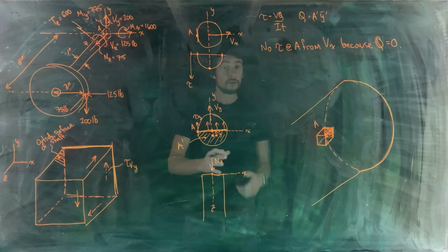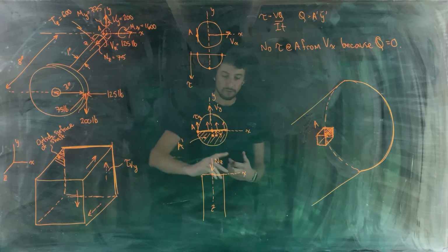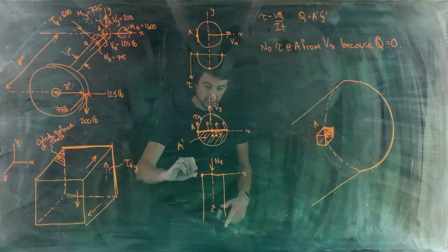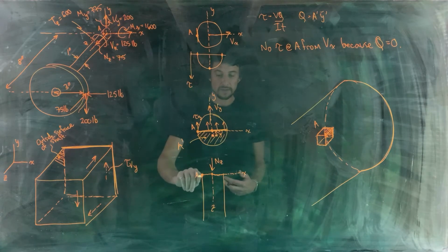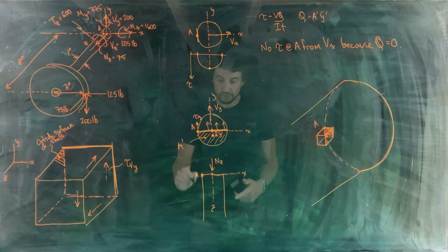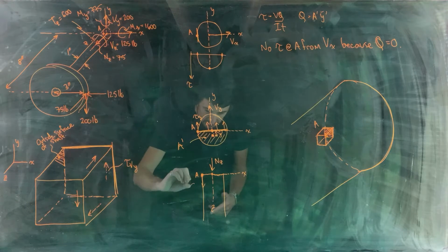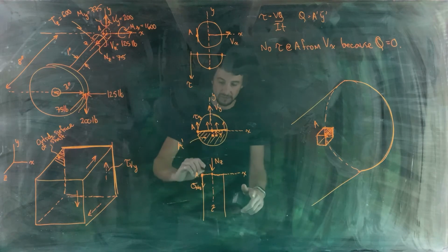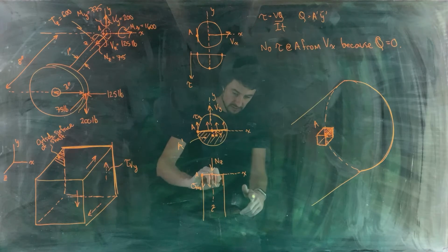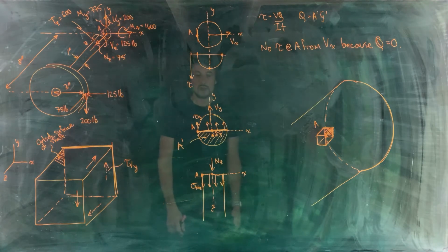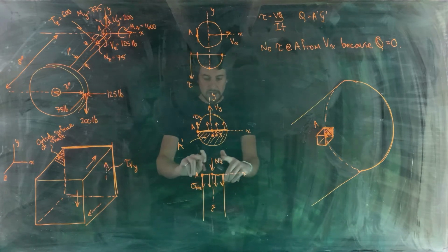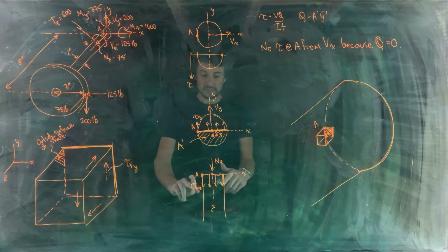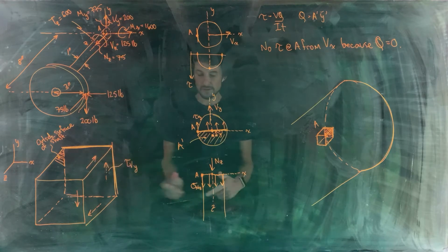Now, an internal normal force is going to create a normal stress. This internal normal force is pressing in on the cut section, so that's a compressive normal stress. So at point A, which is over here, that point is going to be under a compressive normal stress, just like all the other points in the cross section. So every point in this cross section is going to be experiencing sigma NZ, a normal stress due to internal normal force NZ. And that would be true for any other point in the cross section as well. Okay. So again, when you've got things looking like this and you've got your coordinate system here, it makes it really easy to position sigma NZ appropriately on your volumetric element.